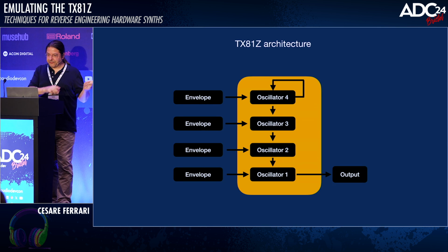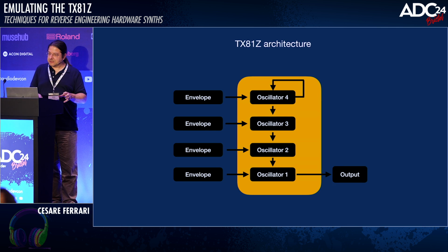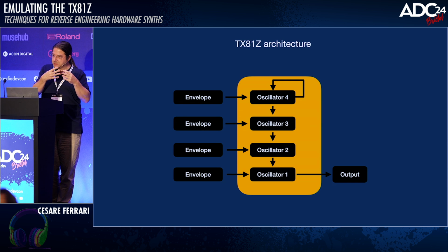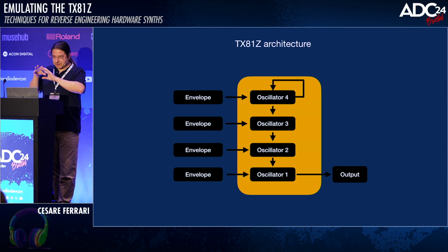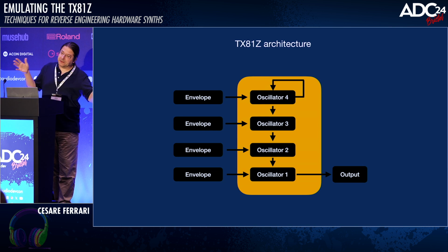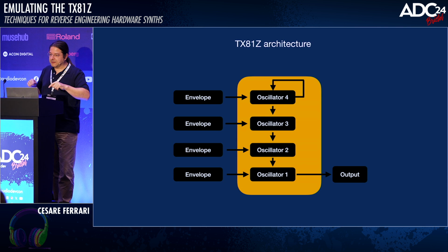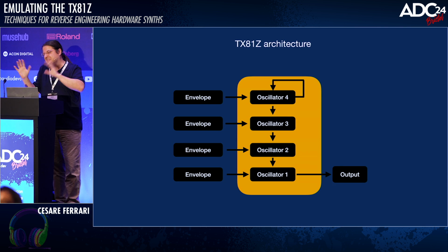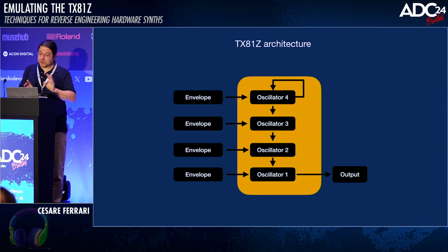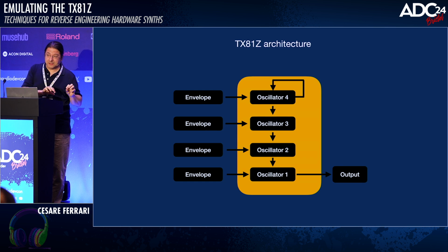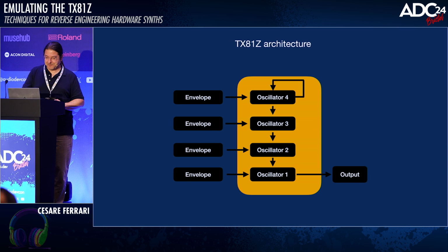So if we go back to that picture before of envelope, oscillator, modulation matrix, it could kind of be written like this, if the sound that we're interested in was the first algorithm, or this particular algorithm. However, I think that's a step too far. I think leaving a modulation matrix in the implementation will give us a lot of flexibility. Otherwise, we'd need 8 copies of this, basically, with the plumbing between the oscillators fixed, and switch between them. It's just not very pretty. I'd much rather have the extra building block in the model. So although we could imagine getting away with only having to implement 2 things, 3, I think, is okay.